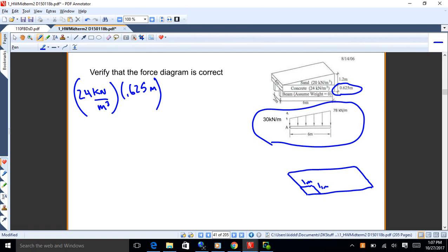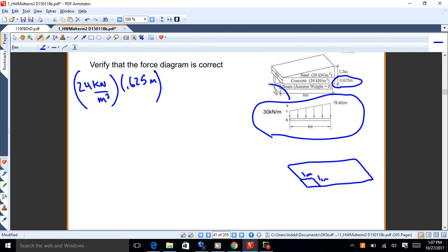But what's happening here is these beams are put 2 meters on center, which means the beam itself supports 2 meters of concrete. So each beam supports that much concrete. So per unit length, each beam, when you multiply that out, supports 30 kilonewtons per meter of length. See? That's how you're walking your way to that number. That's trying to show you a picture of what that means.